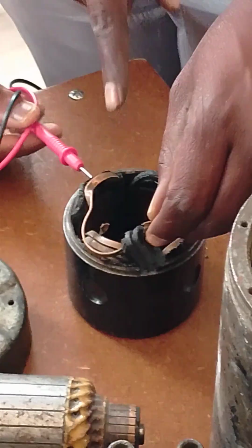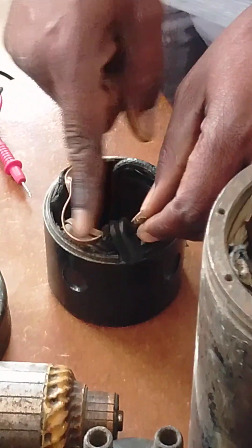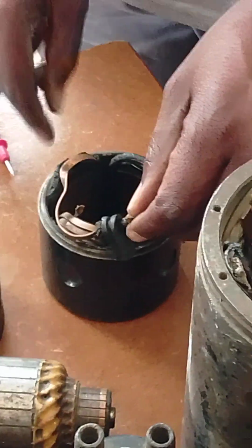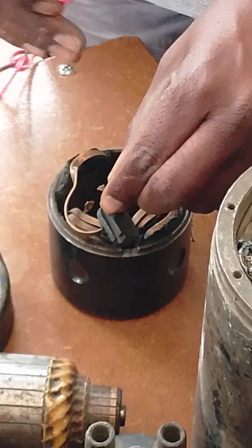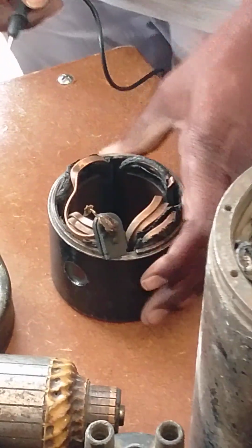There is a possibility that stator motor current will flow through into the housing into ground, because of continuity between the windings and ground. So this is not normal. But obviously, on a damaged component like this one, we expect it.